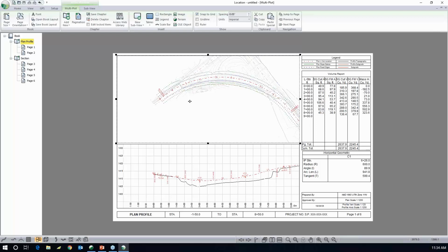The question is, can you display specific cross sections based on your stations? Yes. Another question is, do the drains, retaining wall, and other roadside elements display in plan view? Yes. So you can actually display the actual drains widening. You can display those things in plan view and profile view, but they're not really that great in profile view because they're the same elevation as the drains on the other side normally.